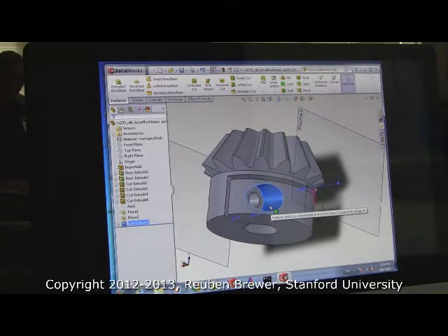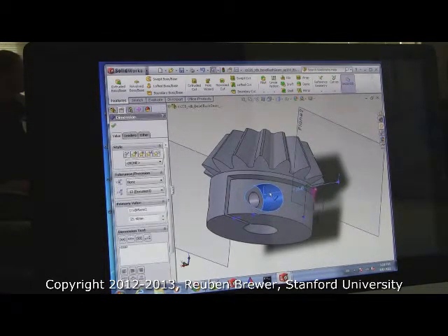Solidworks is quite ornery. That looks good. Yep. Okay, so what happens? Do you have a good sketch? Okay, so select the sketch. And now go up here into the features tab. And now hit cut. You're good.